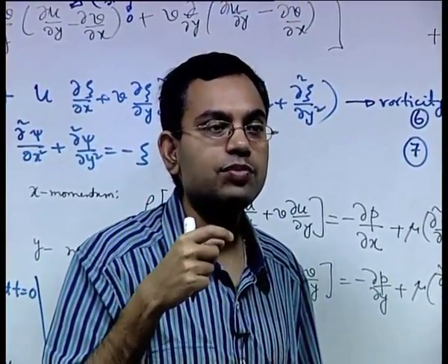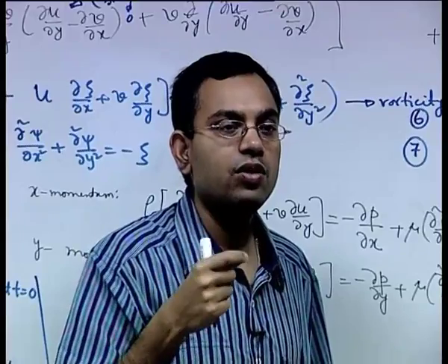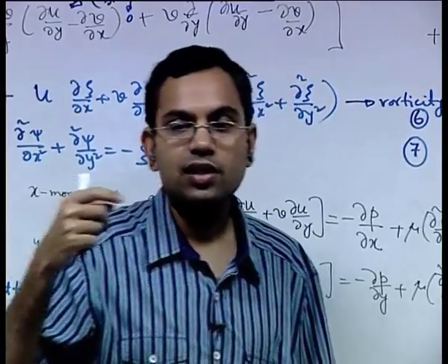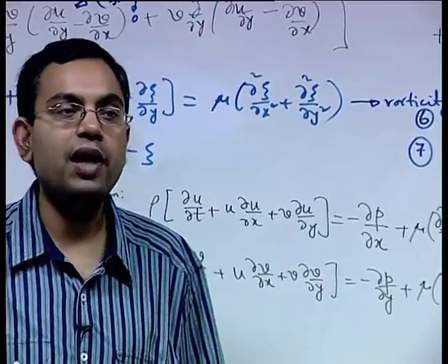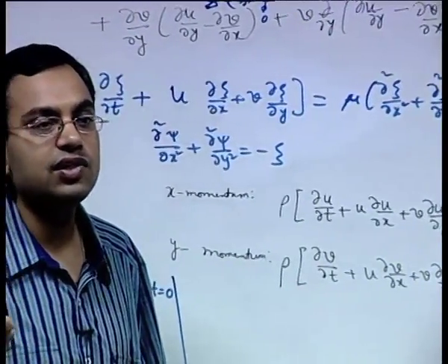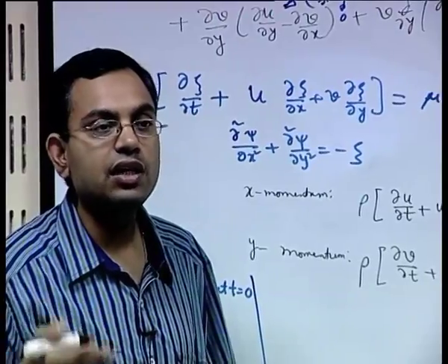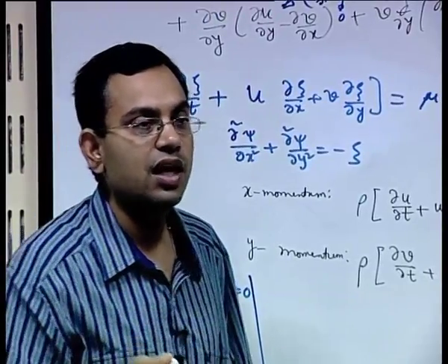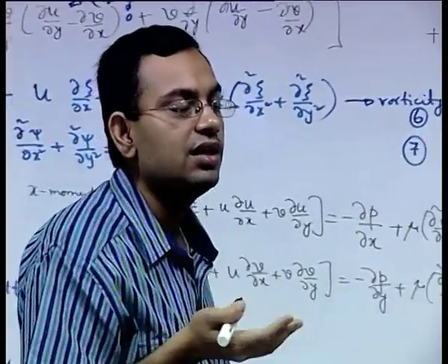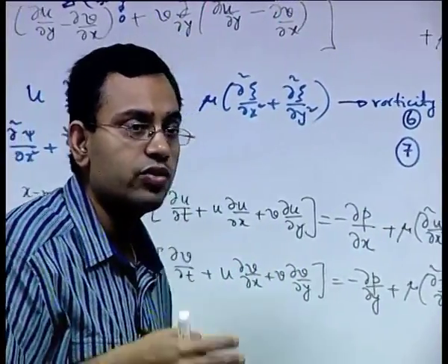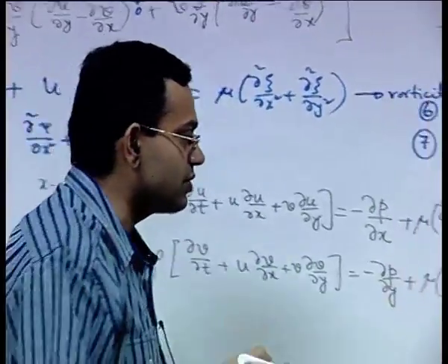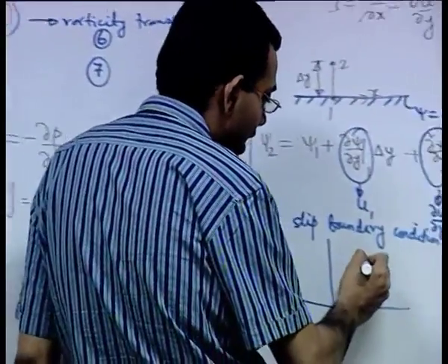So, then the gas molecules can easily escape from their positions which could be occupied in contact with the solid boundary, and there can be a relative motion between the gas molecules and the solid boundary in a relatively rarefied condition. There could be several other possible mechanisms of slip. Now, once you have such a slip,